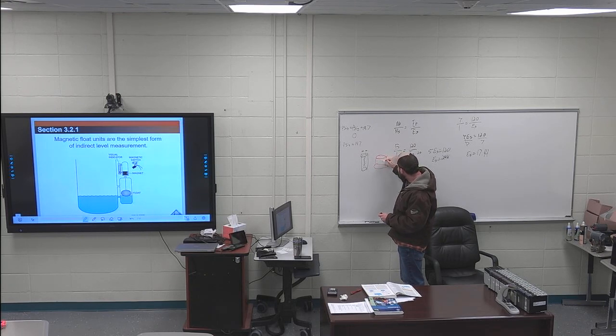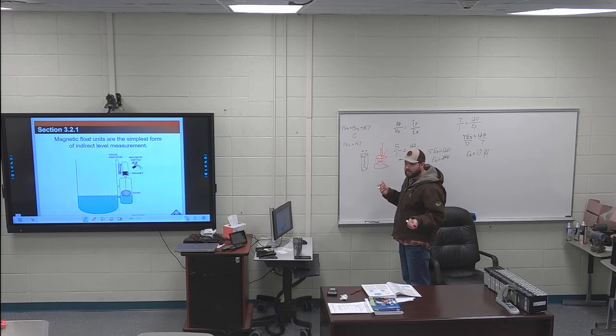It's got a capacitor plate here and a capacitor plate here with a dielectric in between. And then as I push force down on this, those capacitor plates get closer together and it changes the capacitance. And based on the capacitance, I can tell how much pressure is being applied to this. So capacitance changes based on the distance between the plates. Right?